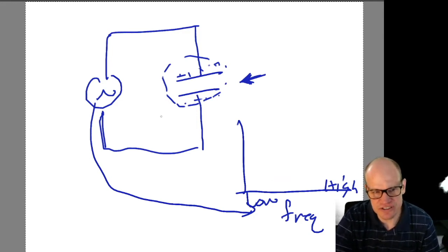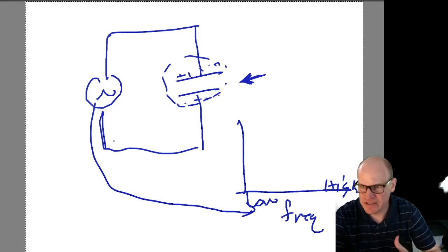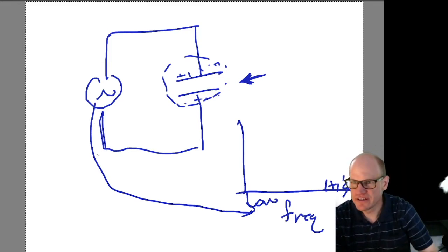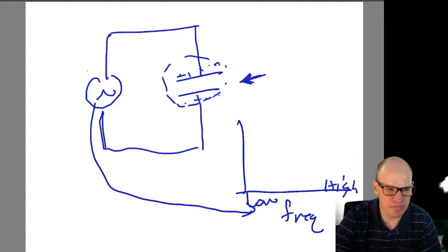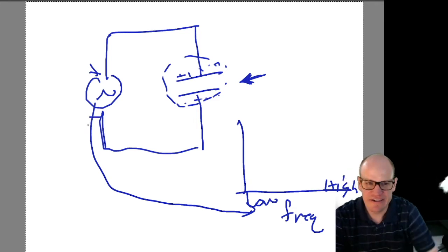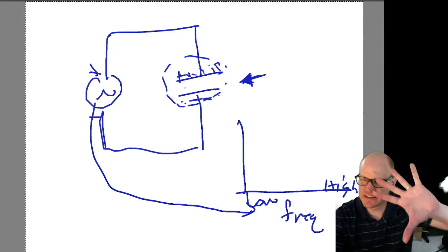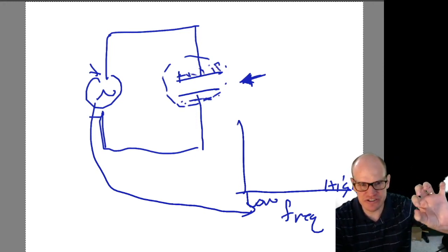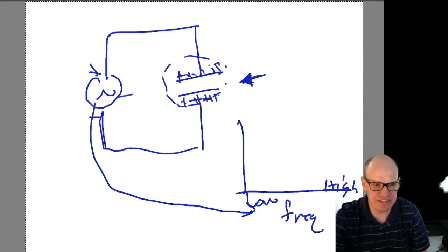So with AC circuits, if this is a really low frequency, it's almost like a direct current. If it oscillates once every year, then for most of the year it behaves like a battery with a direct current, with the positive voltage here and negative voltage there, and then six months later those signs will switch. So at very, very low frequencies, this acts like an open in the circuit, and so you're going to build up charge, and then as it switches back over, these charges are going to dissipate, and then it will build up charge in the opposite direction, matching this right here.